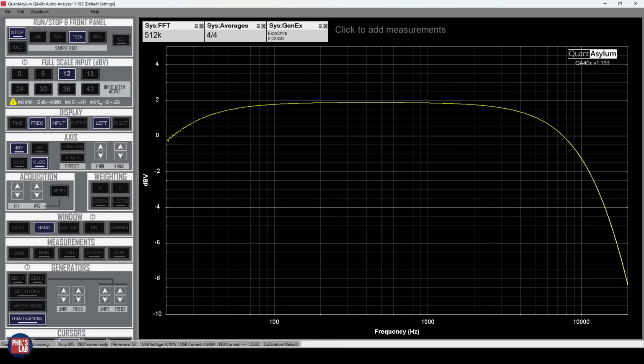And for an audio system, if this were a headphone amplifier, we would definitely want to increase the upper cutoff frequency. But since this is for guitar, this was specifically chosen to have a slightly narrower frequency band. So for guitar, we might only have several kilohertz as our maximum. So 10 kilohertz seemed like a fairly suitable cutoff frequency. And it's good that we can use tools like this to verify our frequency response.